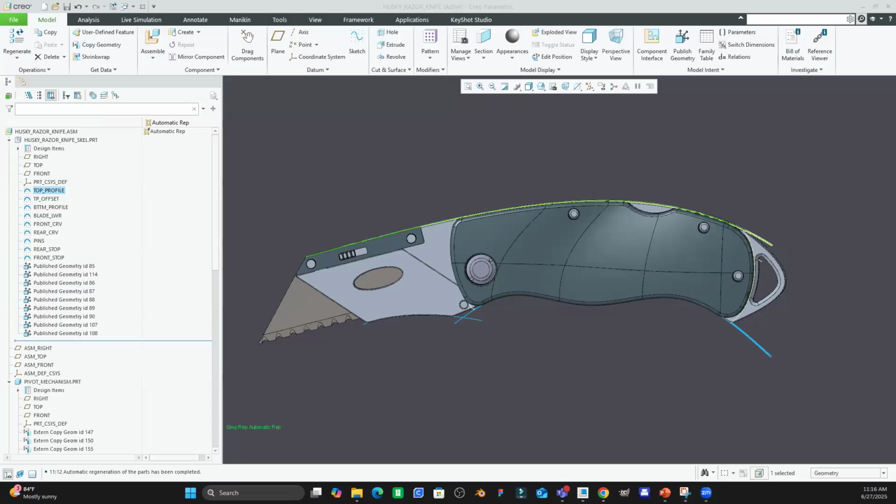Then we cut every part, maybe using merge inheritance, or we use copy geometry to different assembly parts. Then we assemble it together using the same coding system. So when we modify the ID master, it can generate all the different parts all together because it's all related to the ID master part.